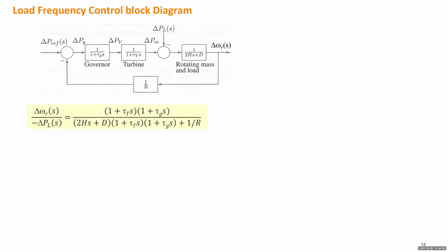So now we can draw the entire closed loop control by considering each component as a first order system. Here we ignore all the nonlinear functions, maybe limit or deadband. We just model the time constant for each part. This will be the simplified model to talk about this entire control loop, which is good for this section, because here we only focus on small disturbance. But later, when we want to study transient stability or other stability, we may need to gradually add more nonlinear components to make this loop more complex and more accurate.